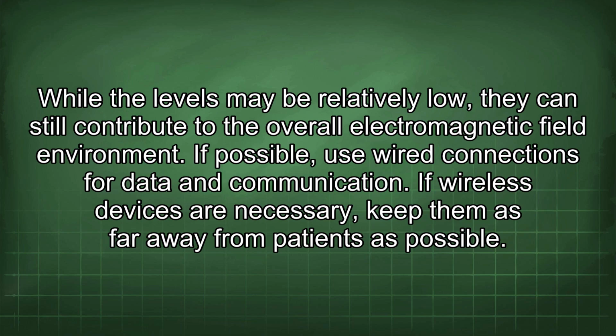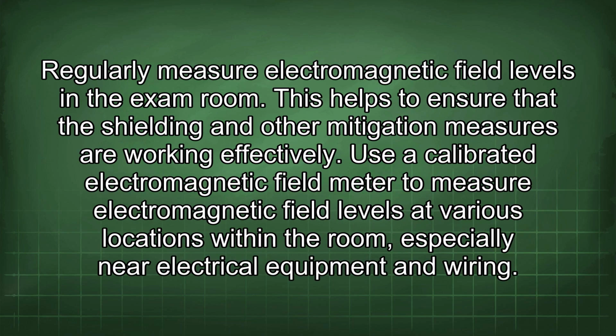If possible, use wired connections for data and communication. If wireless devices are necessary, keep them as far away from patients as possible. Regularly measure electromagnetic field levels in the exam room. This helps to ensure that the shielding and other mitigation measures are working effectively.